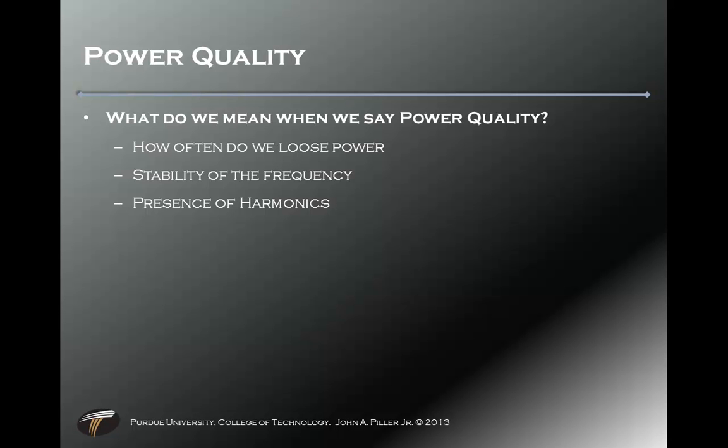And then there's the presence of harmonics. Harmonics can cause extra loading and overheating of equipment, and we cause harmonics along the line because of devices we plug into the system.